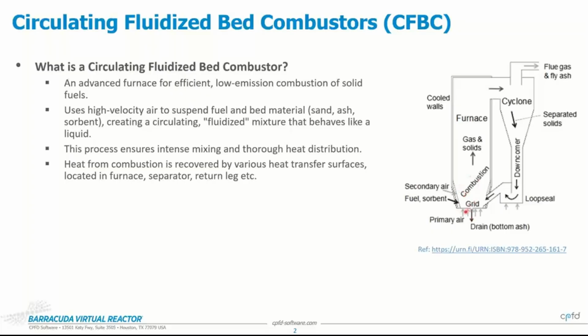You start fluidizing the bed. If the fluidization operation is working properly, you basically see a well mixed system, which ensures that there's proper contact time between the gas and the solid, helping with the combustion process. Again, if the solids are circulating well enough, you should see a uniform heat distribution in the riser without any hot spots in it. And once this process happens, the combustion takes place.